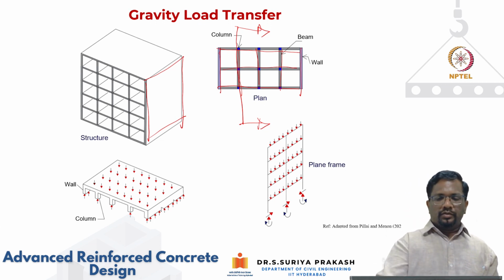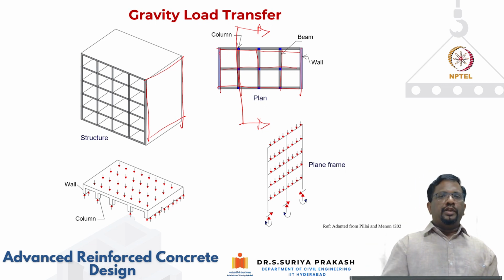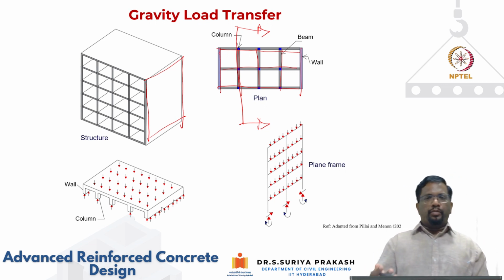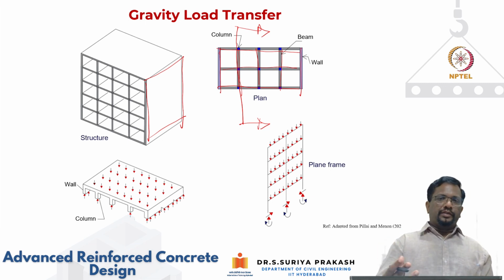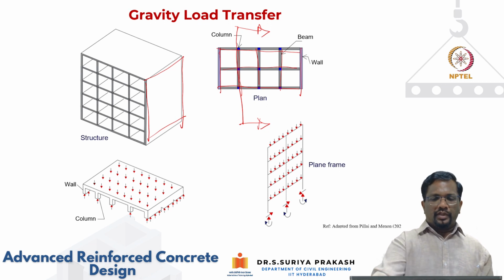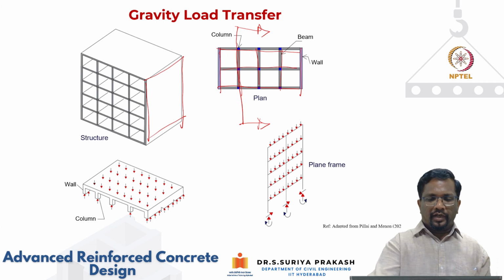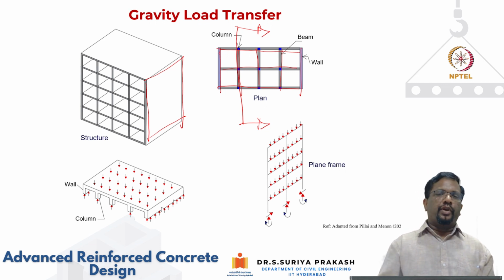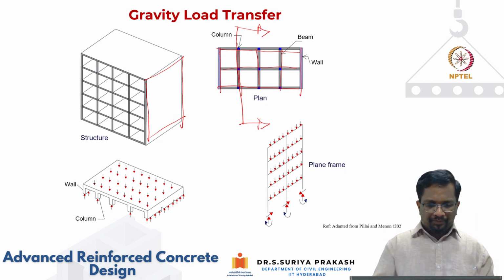Okay, so this is from typical structural analysis. If you know what kind of loads you're designing for, usually design codes will help you. For example, IS 875 has different parts: part 1, part 2, part 3. That gives you guidance on what kind of loads we need to consider. Depending upon what we have considered, from simple tributary area we can calculate, at each floor level for that particular frame, how much load is getting transferred, right?